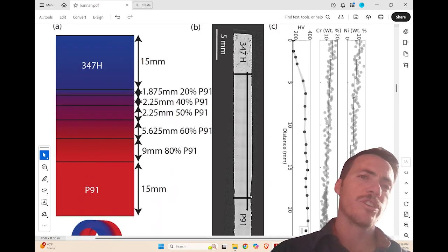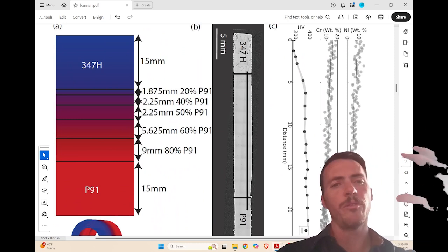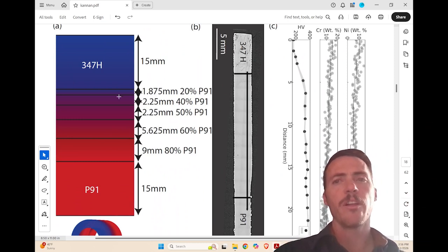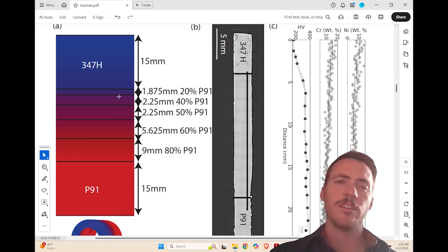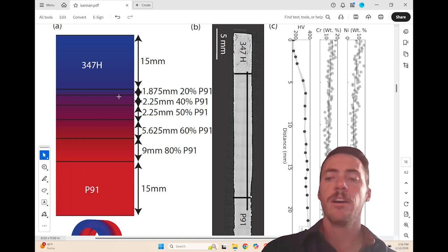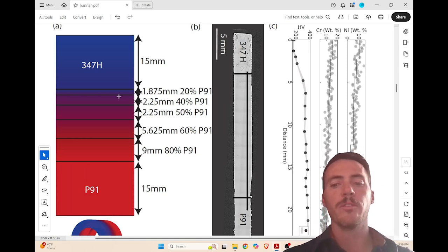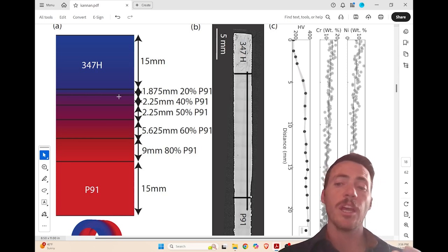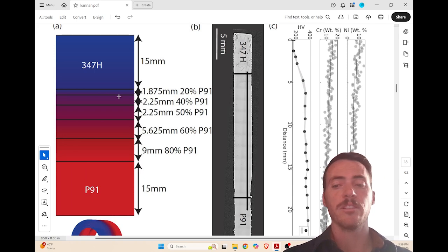And the second thing I want to show here is this figure where they're actually showing, again, the design on the left, what they expected, and on the right, you're actually seeing the transition profile, where you can actually see the residual stress. They were able to get the improvement, like less diffusion, less carbon loss, and they didn't get higher residual stress, which is important because you would expect that to be a bit of a trade-off between those two things. Here you're able to get the diffusion benefit without paying any mechanics penalty, which is exciting.